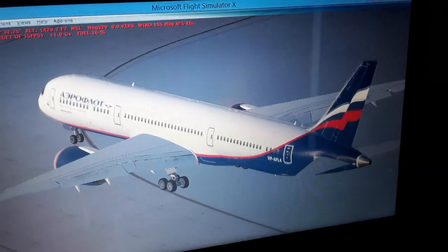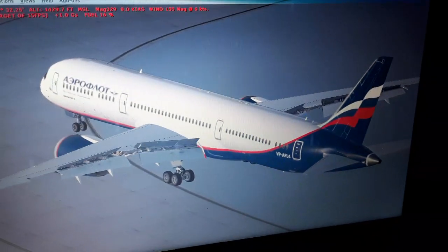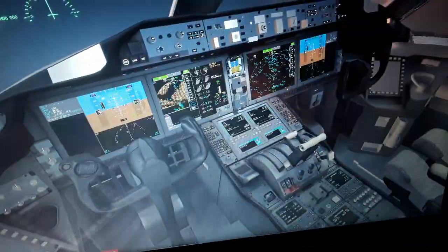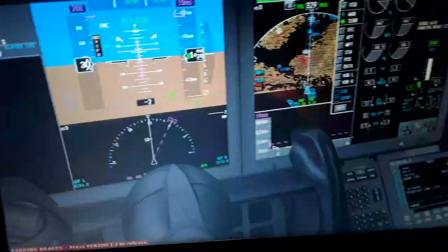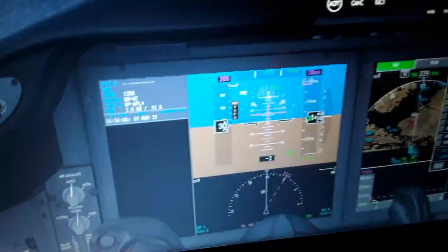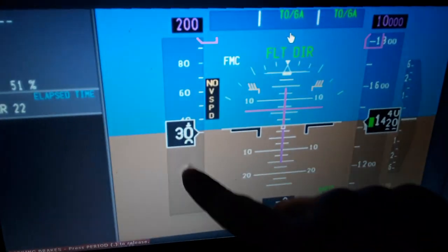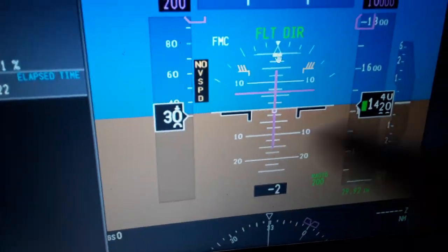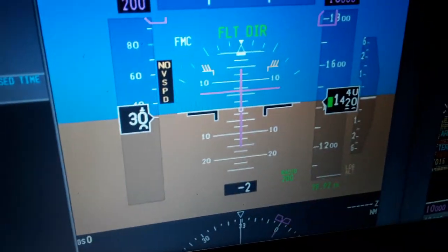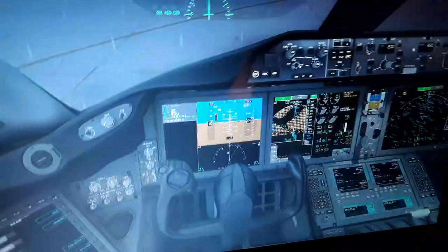So in order to avoid the stall over here, you monitor inside the aircraft all the time. You can see the airspeed indicated over here, the airspeed table, and we have the stall speed is displayed just below the airspeed with a red and amber or yellow indication over here.